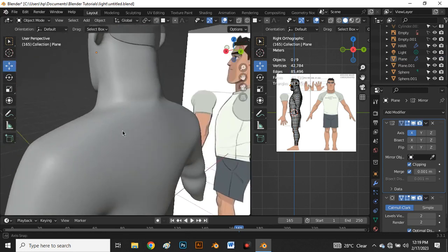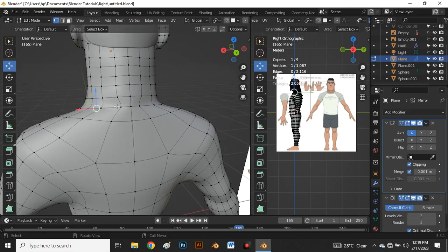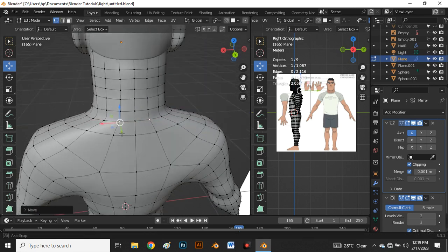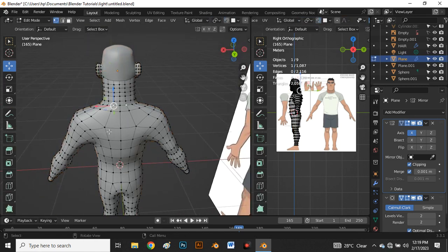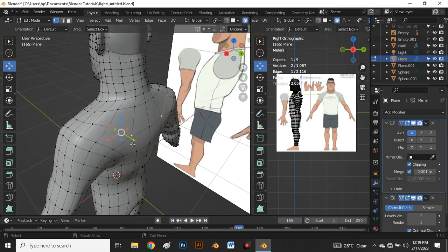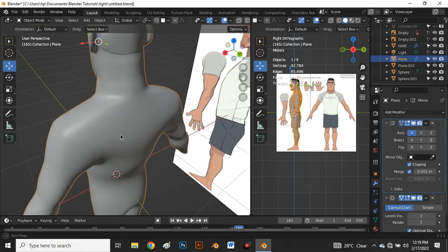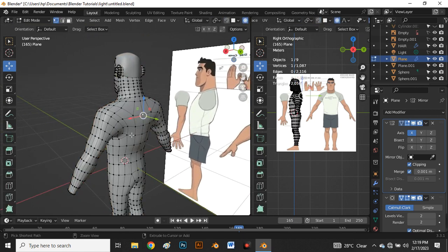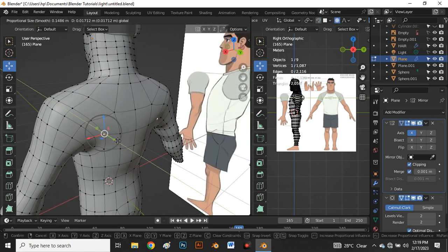So this is our character body joined to the neck. So we can have some issues here. Say Tab for edit mode. Move these vertices this way. Be very straight. Tab for object mode again. Proportional editing, and let's move this back a little bit. So you can select this also and make some tweaking here.